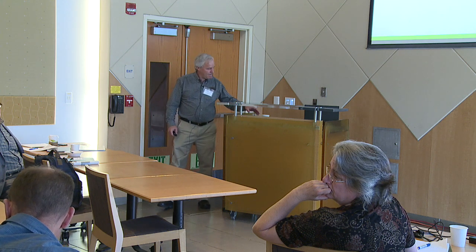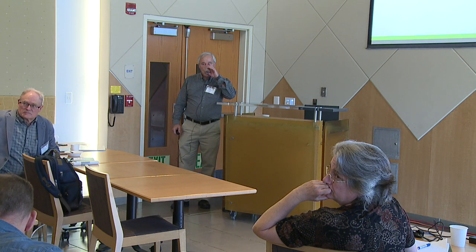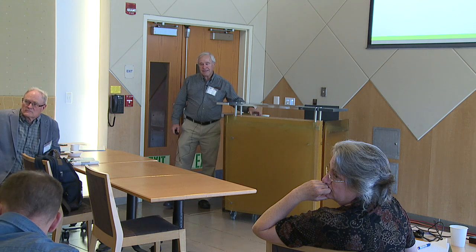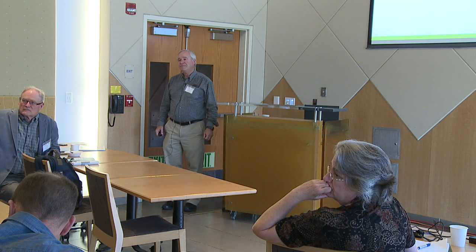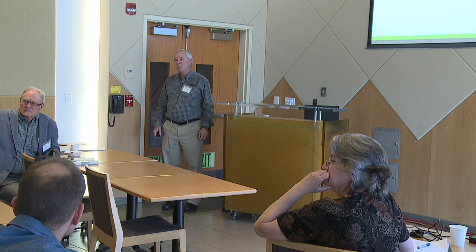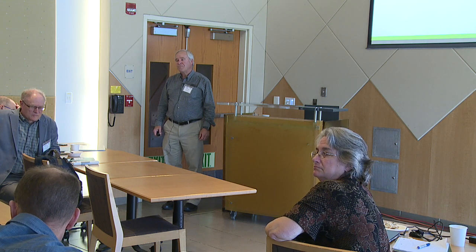No, I understand it. Your diversity. So as the load changes. So on the way up, static pressure set point, and the box, let's just say it's an undersized box, just to make this conversation correct. It's an undersized box. It's never going to have enough static to deliver to that space.